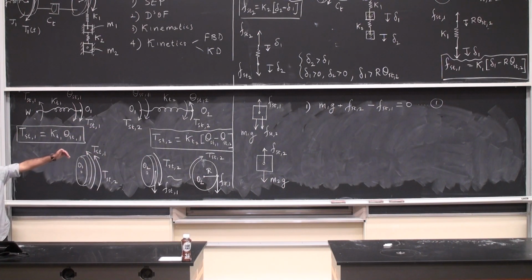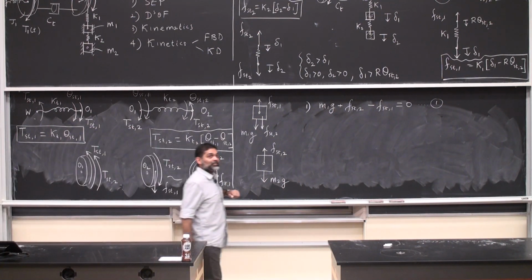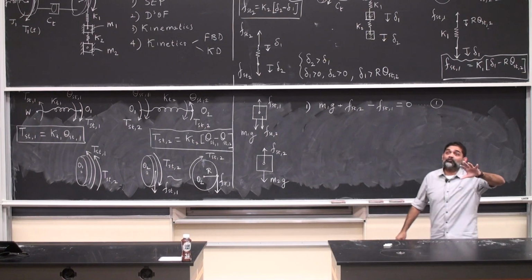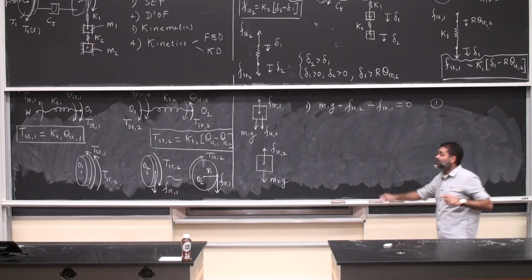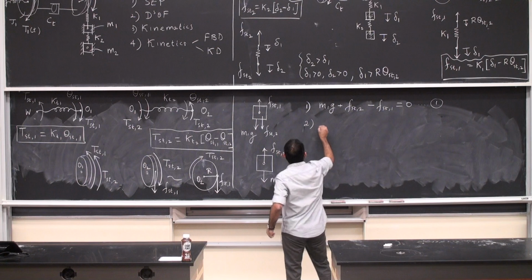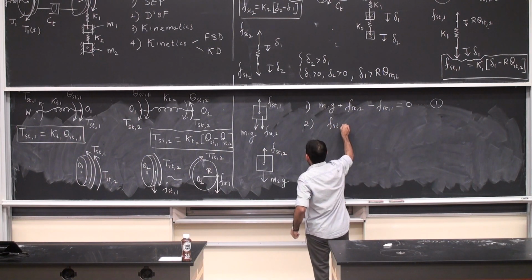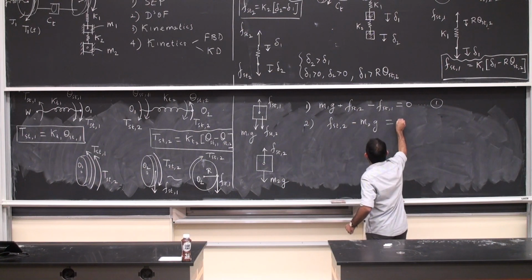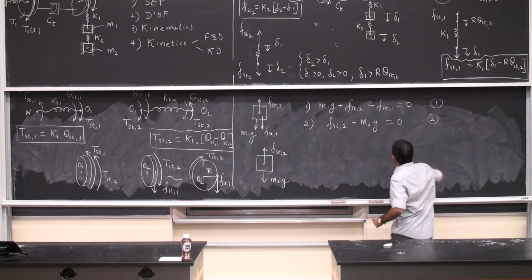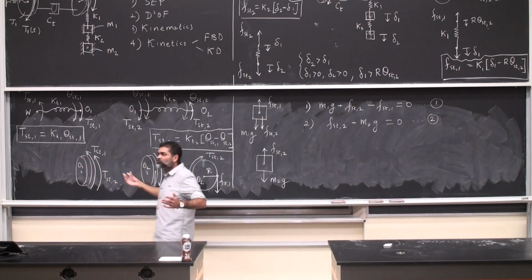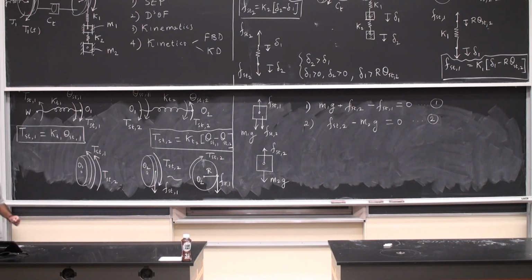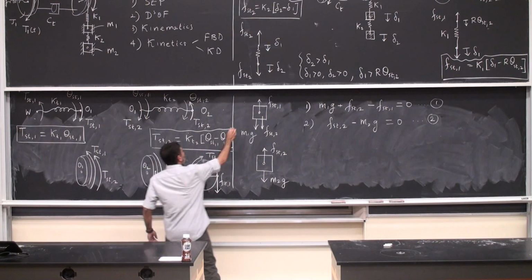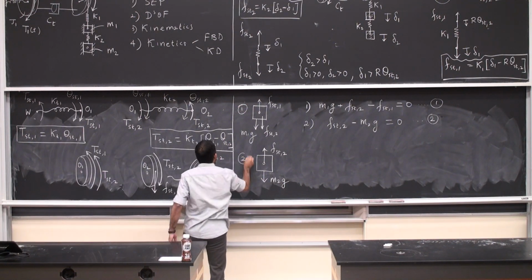Then from the second mass that I've drawn, as you can obviously see, F static 2 is equal to M2G. There are no applied forces, there are no applied torques because this is at static equilibrium position. Minus M2G is equal to 0. It's either M2G minus F static 2 is also equal to 0, same thing. Then that's from here.